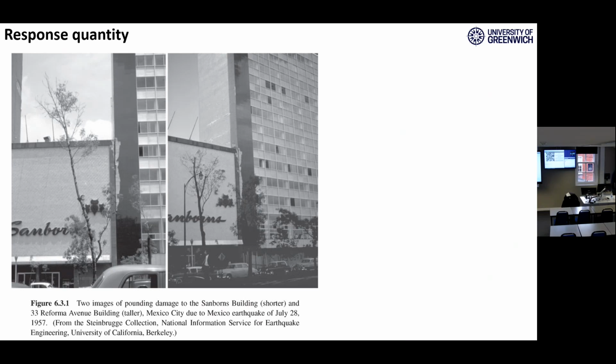So that's why in most design codes, it's necessary when you're constructing your structure. You have a neighbor, you have two neighbors. You should construct your structure like this. You need to have a gap between this neighbor and this neighbor. Otherwise, you will have pounding during the earthquake. So that's why it's important to understand how we can calculate the deformation of these two structures. And these deformations should be limited in a way that they don't pound during the earthquake.